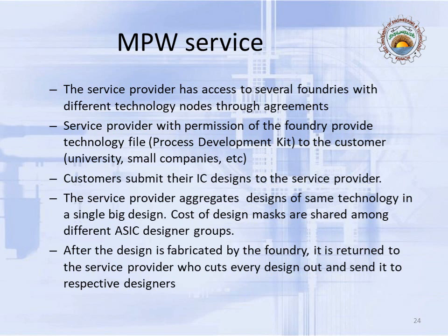It's actually a pooling service. MPW service providers are pooling service providers. So let's say we are sitting in Pakistan, we have made an IC design and we want to get it fabricated. What we will do is contact a multi-project wafer run service and send them our design. The multi-project wafer run service also contacts other small companies, startups, and other universities. So for instance, they get one design from Pakistan, one design from India, another design from Israel, another design from a small startup in South Africa. What they will do is combine all those designs together into one big design and send it for fabrication to a foundry. And let me tell you, it's somewhat similar to what we do for PCB fabrication.